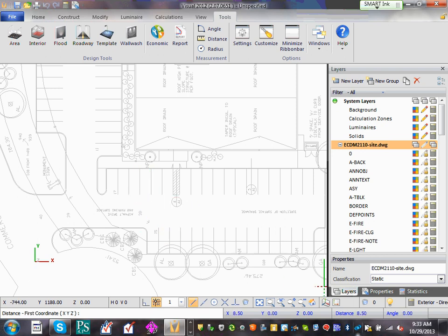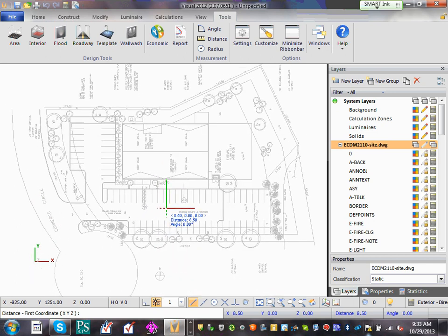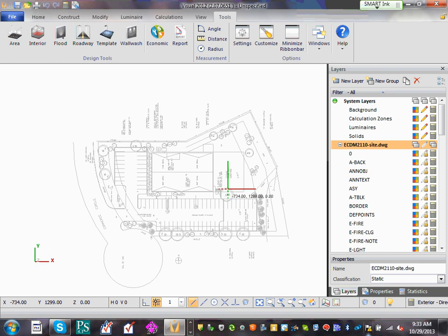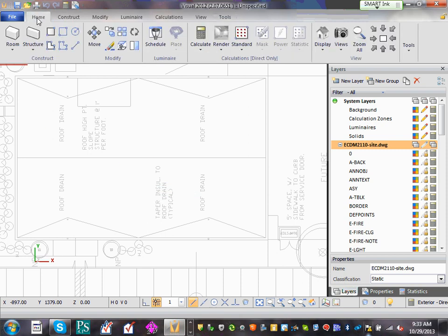Verify the scale. I was just checking. Your parking stalls are 8.5 foot wide, which are normally 9, but maybe for this because it's small, it's compact car parking or something. You're fine. It's not far off. For this, you have a future section and then the actual building. It doesn't factor in reflectances, but sometimes it's good to have the building there because otherwise it'll let light pass through the building. If we put wall packs on here, it'll actually spill light behind the building.